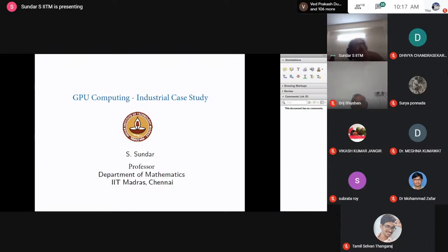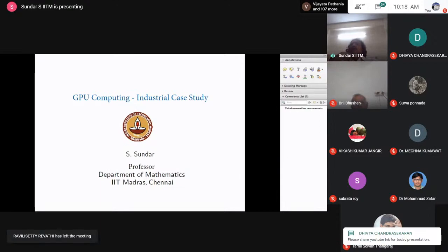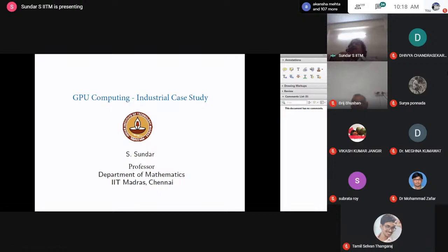That's the main thing. But every problem needs its own treatment. So what I'm going to talk about today is our own experience on direct industrial problems and what the fluid dynamics models are. Then, because my focus is on GPU computing, how you compartmentalize your entire computation, and in each compartment how much computational speed you are getting.